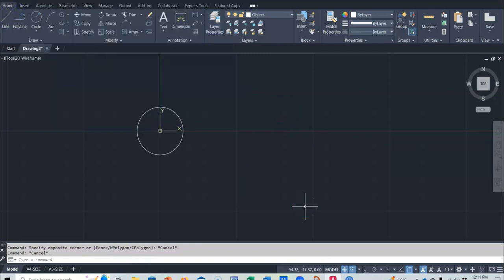So there's the circle. The other thing you have to put in is the hexagon. This is a good opportunity to use the polygon command. If you don't see it, it's up there with rectangle. Again, it says the polygon, enter the number of sides. Ours is a hexagon, so it has 6 sides. And we're going to specify, start to draw it.